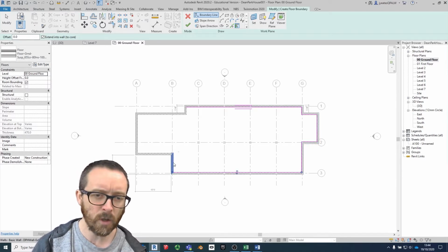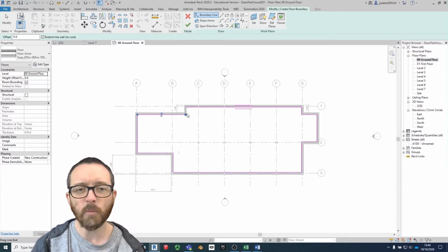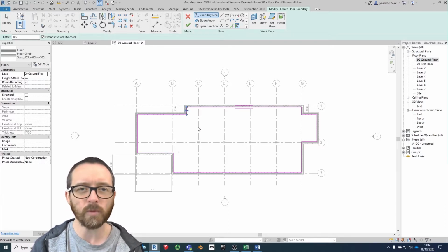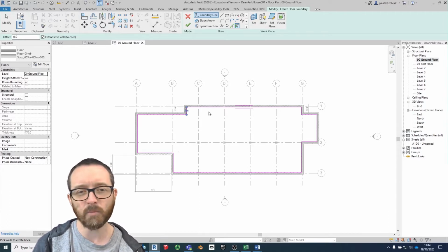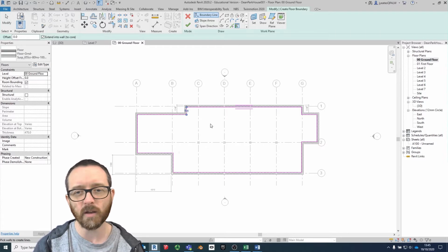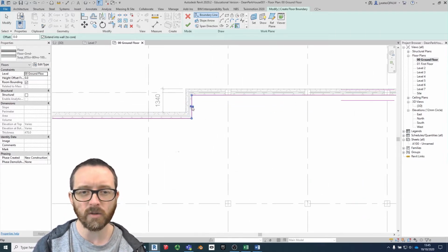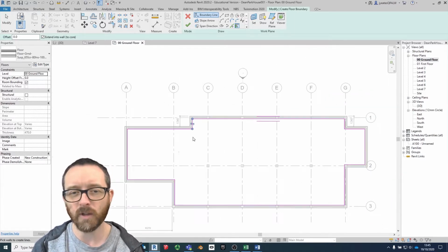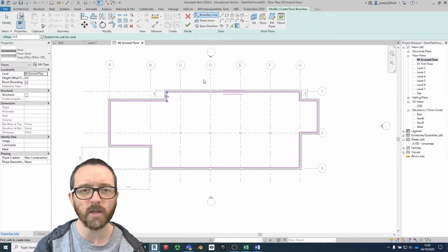Now roofs and floors, it's not so important about the clockwise, it's just more important going clockwise when we are drawing walls, because walls often have a render for the exterior and a different render on the inside, and it's easy to flip them around. If you've drawn them in the wrong direction, you can just press these 2 directional arrows and flip it around, and everything is sorted out. But it is expecting you to work in a more clockwise fashion.